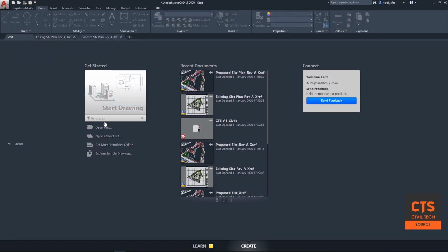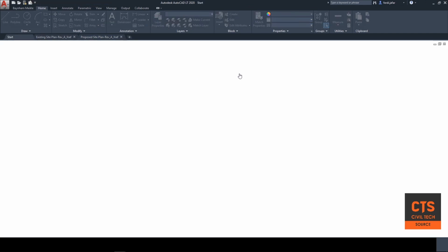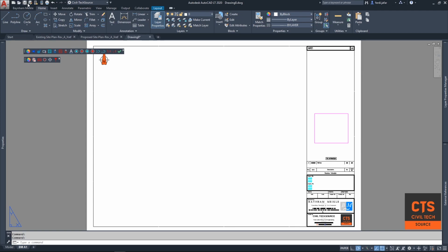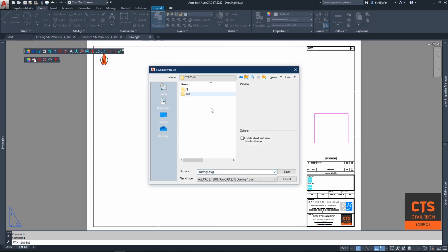And we're going to open a new drawing, which will be our engineering drawing. What we can do is go ahead and save it in the civils folder, and we can give it the name, the project number usually. Let's name it this project 001, and then we give it a 000, which is the drawing number, and then we type template. So basically every time you want to create a new drawing for that project, you will just open that one and everything will be set up from there, and then you just save as on top of it.